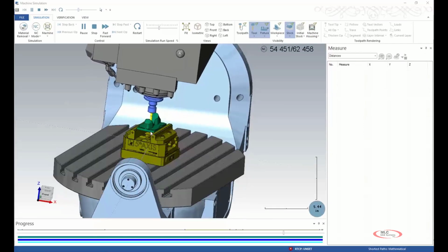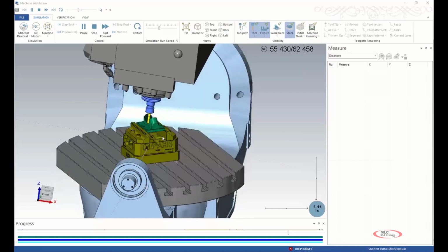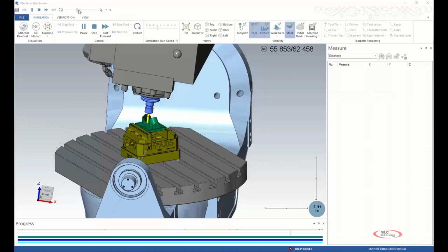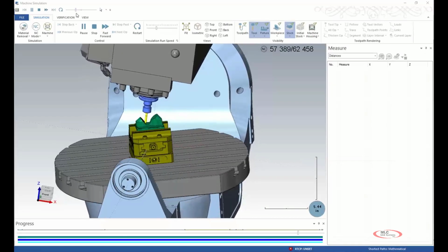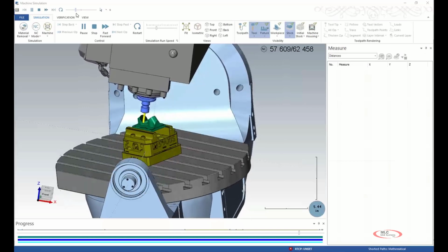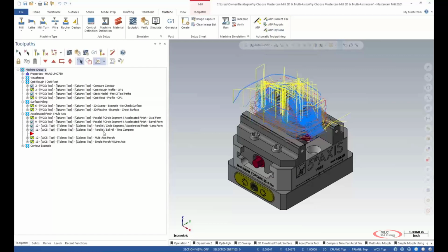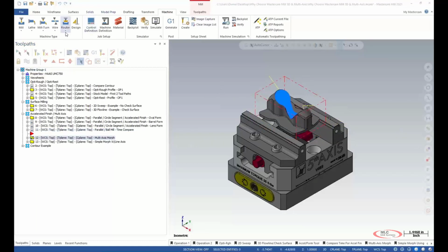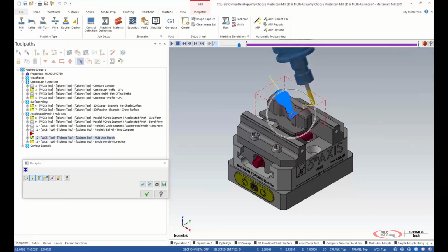Now, the table is flipped around, and Mastercam is starting to force the tool up the left side, which it just came down the left side going right. So this is the reason why using the simulation could help with any kind of collision, but you can also see what your tool's actually doing. Where if I verify this toolpath, let's go ahead and step back. We'll say that was our morph here in the middle. If I just backplot this or I verify it, it doesn't matter. What we're going to see is the tool just following the part like this. We don't see the actual table flipping around 180 degrees once it gets to the center.